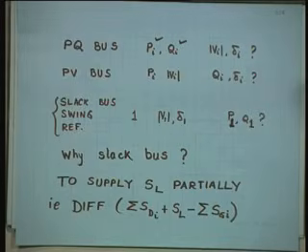The whole idea is to keep V constant, and V can be made constant by so many means. The voltage control you must have studied in your undergraduate. So, you know what is static var control, you know what is FACTS, you know what is a dynamic compensator, you know what is a synchronous motor running at no load, that is a dynamic compensator or synchronous condenser. There are several ways by which you can call these controllers: static controller, dynamic controller and so on.